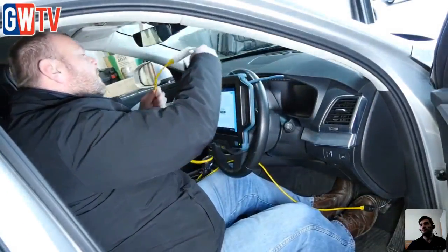One of our most popular requests at the moment is for the PSA group with the alternator stops charging. And what it is, it's just simply a software update to the engine ECU. But a lot of people don't have access to the PSA dealer side, or their dealerships are too far away, or they're too expensive, and so on and so forth. So a lot of them will just come in, give us a call, say that they need to do the update because it's part of a bulletin, and we'll carry that out for them.